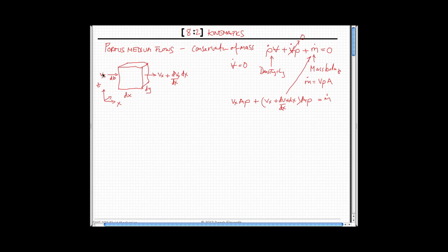The velocity, it's into the system. The sign convention says if it's going into the system, the unit outward normal is negative, so this is negative. What's the cross-sectional area of flow? Well, it's going to be this area here, which is the same on both sides. So area is going to be equal to dy times dz.